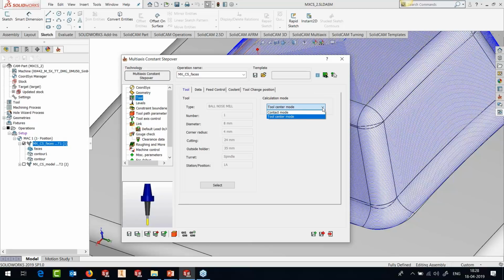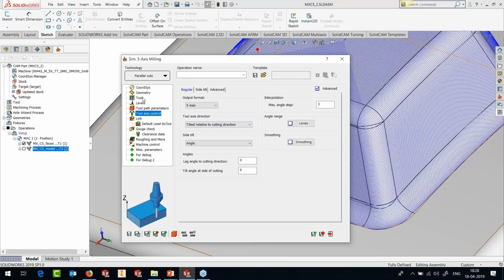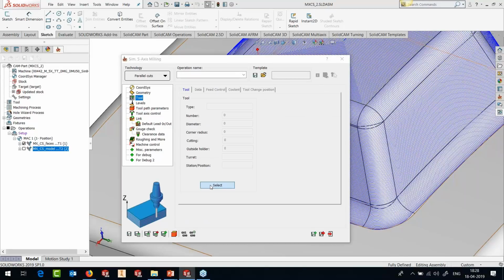If you go back again to your generic 5-axis calculations, whenever you don't get good toolpaths using the auto mode, okay? So if I go here and add a generic toolpath, okay, let's select a tool, otherwise it will not ask me.